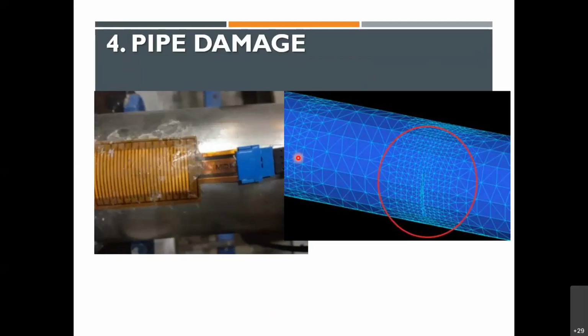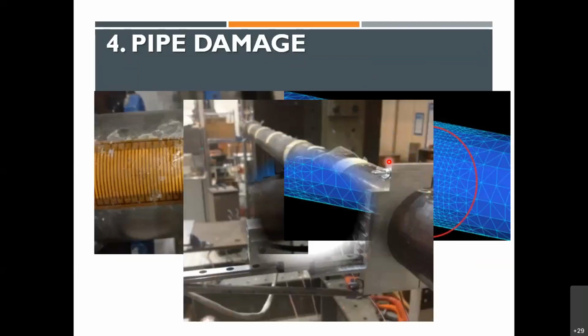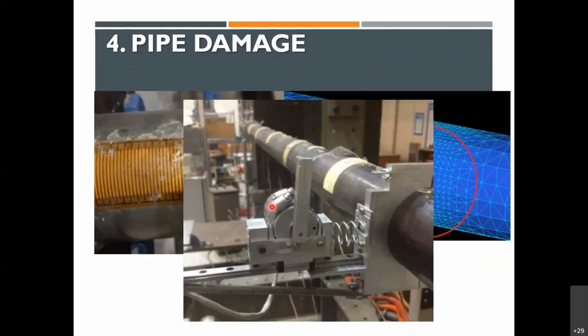Then the idea was, okay, can we detect pipe damage consistently or not? And this was done at Rice University in Texas. This is probably the simplest of all, but this is to demonstrate it can also be very simple. We just slapped in some PVDF patches all around, but modeled those damages with a nice 3D finite element simulation, and we excited with a motor with an imbalance at various frequencies.